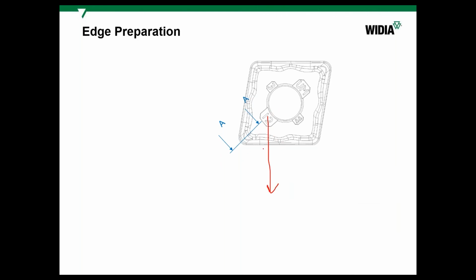Basically, if the chip breaker is more developed here than here, the chip is going onto the right face, and here is the most developed chip breaker, and the chip control is much better. Chip creation, segmentation is better. Here, it's not that good. So if you cut only this part with a small depth of cut, the chip will not go directly, some part of the chip will try to go there, and there is no barrier, you can see, and also some will go there, and it will complicate the direction of the chip. So it can be not ideal here.